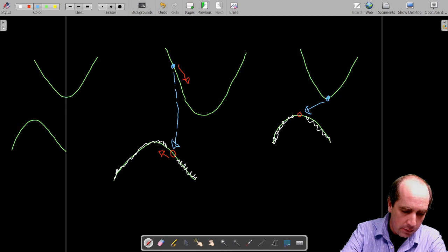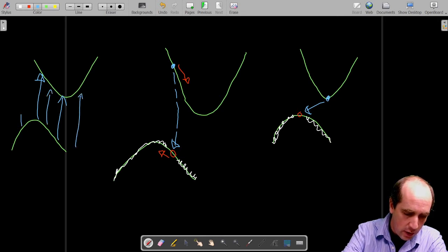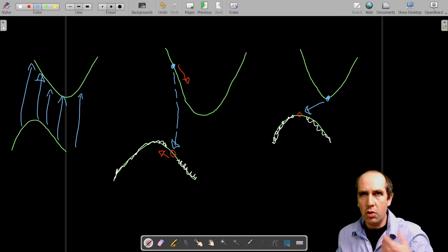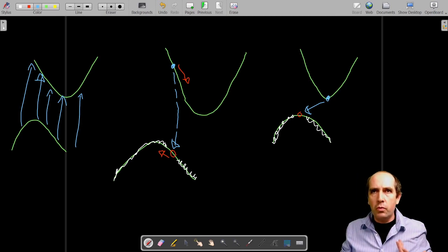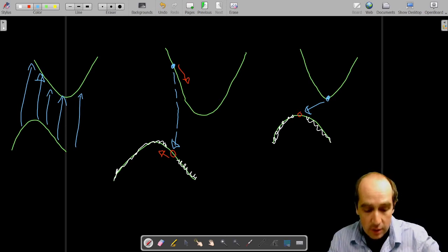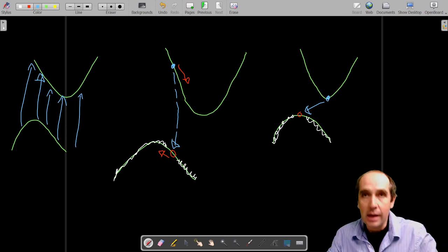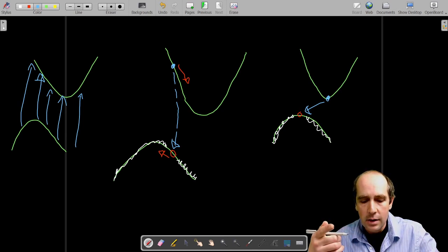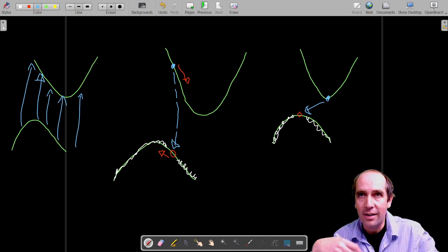If the photons have enough energy to produce transitions up, as long as they are vertical, all of these transitions are allowed, and not just allowed, they are quite likely to happen. What is not really the case is the recombination, the transitions that produce light. And this changes things significantly in terms of constructing light emitters, and this is what we will discuss now.